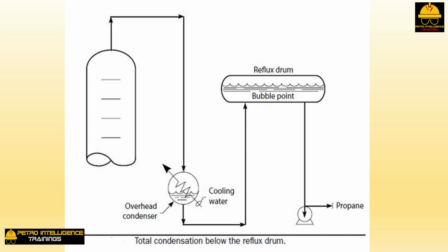The liquid leaving the condenser is subcooled. The liquid entering the reflux drum is saturated liquid at its bubble point. Of course, the temperature of the liquid is the same at both points. The subcooled liquid is subcooled in the sense that its pressure is above the bubble point pressure at the condenser outlet temperature. It is this extra pressure, above the bubble point pressure, that may be converted to elevation.